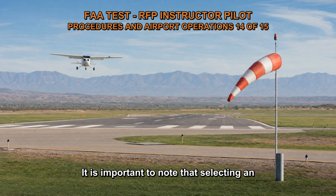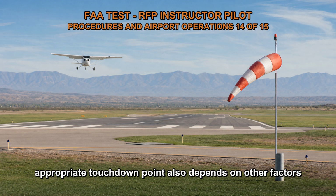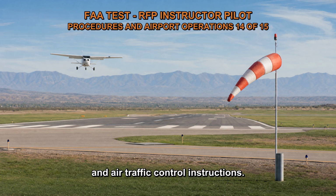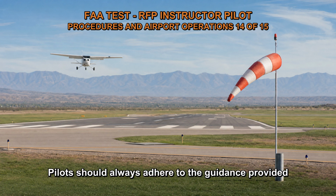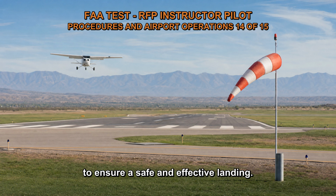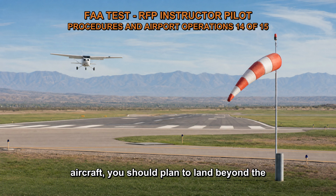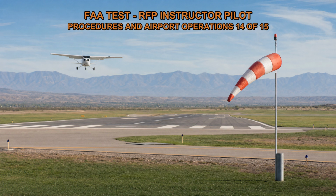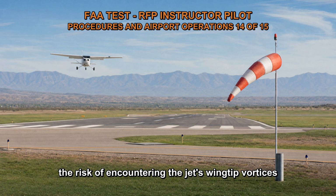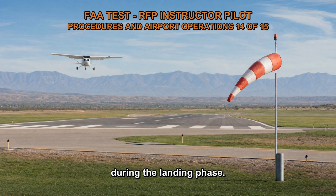It is important to note that selecting an appropriate touchdown point also depends on other factors such as aircraft performance, runway length, wind conditions, and air traffic control instructions. Pilots should always adhere to the guidance provided by air traffic control and exercise good judgment to ensure a safe and effective landing. In summary, when landing behind a large jet aircraft, you should plan to land beyond the jet's touchdown point. This strategy allows for safer separation and minimizes the risk of encountering the jet's wingtip vortices during the landing phase.